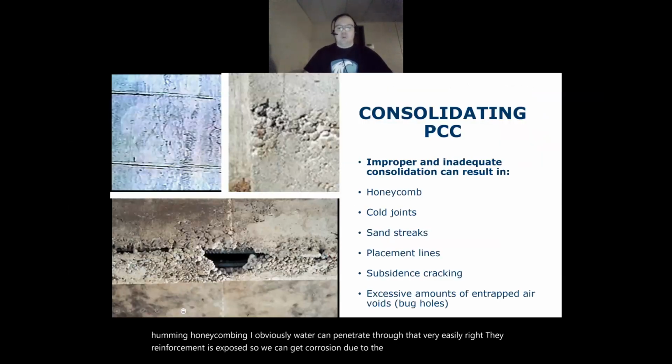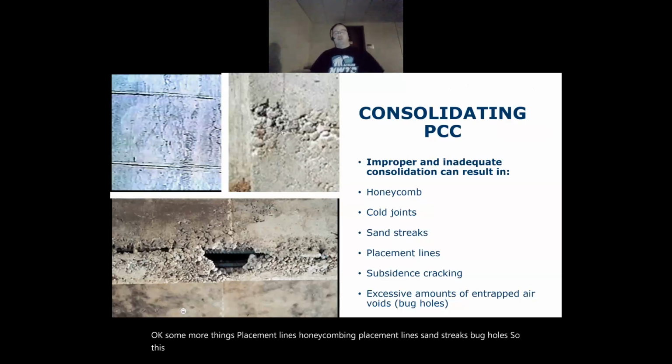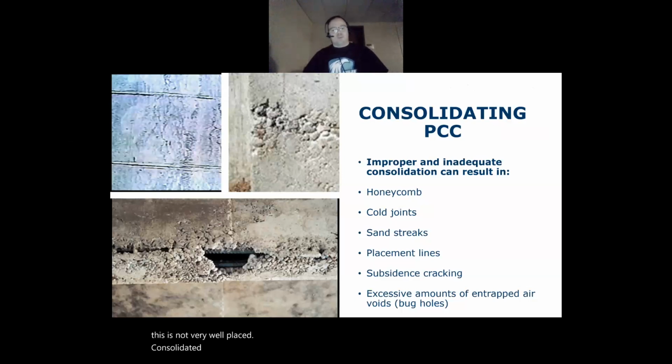Some more things: placement lines, honeycombing, sand streaks, bug holes. This is not very well placed, consolidated concrete. So it's another skill for those contractors and workers out there, properly placing and consolidating that concrete.